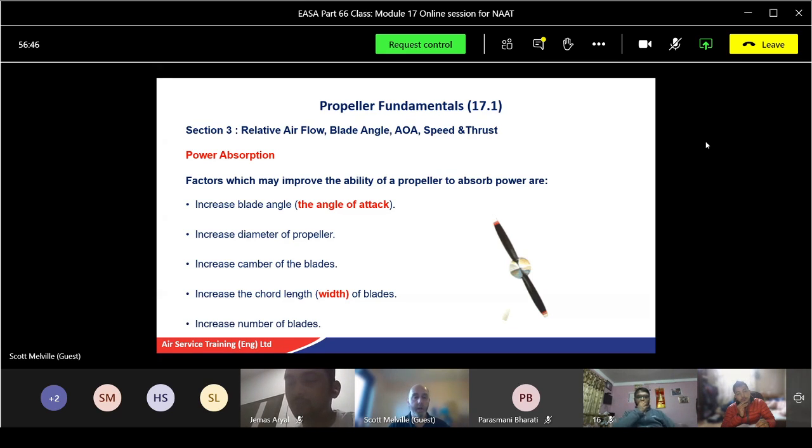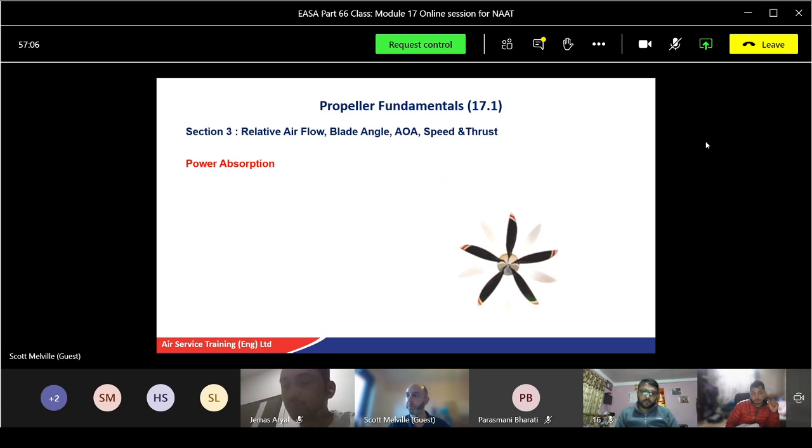Or simply add another blade. So you can make that a 2, make it a 3, make it a 4. Again, pros and cons both ways. More blades, more power. More blades, heavier. Heavier, more fuel. So it's down to the designers to design the correct blades for the engine. Okay. So like there, put more blades on there.